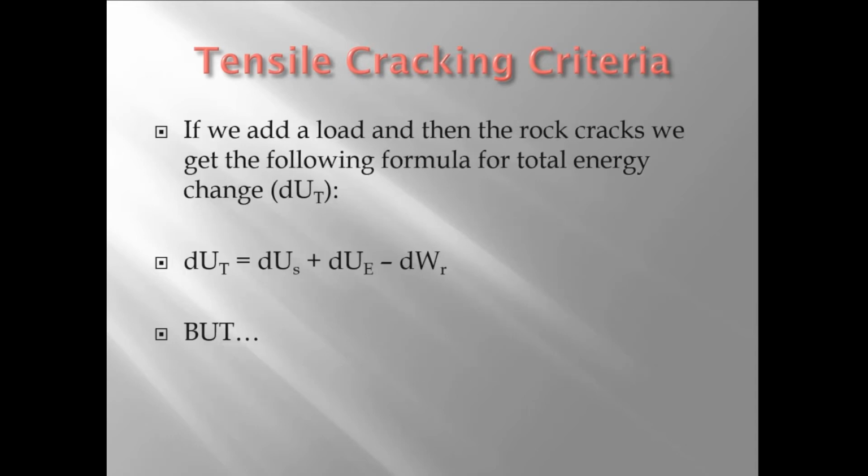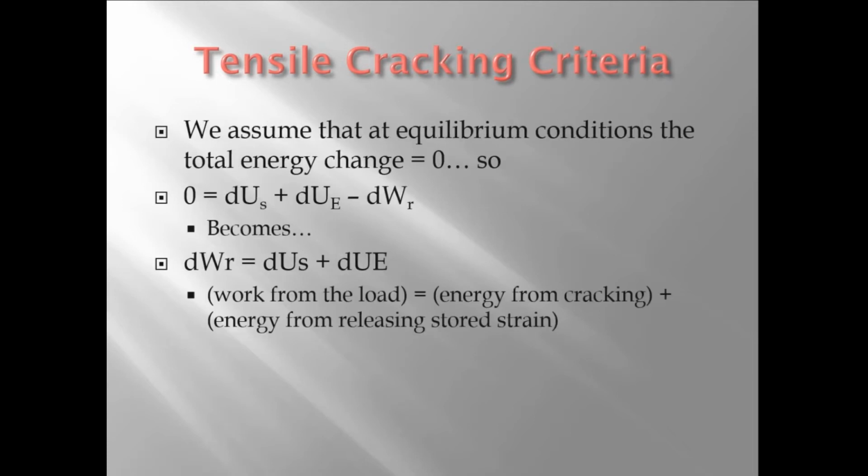You can set up equations that show the different parts of the energy and the load applied. And if it's at equilibrium, there's no change. Therefore, it's just shifting where the energy is. The energy goes from your applied load into something else when it breaks. Specifically, it releases all that energy into the energy of the crack surface.